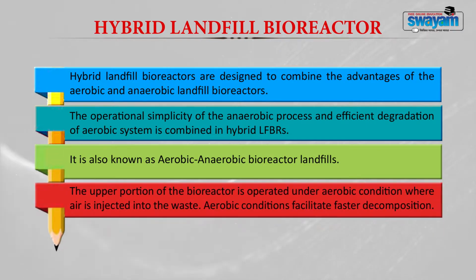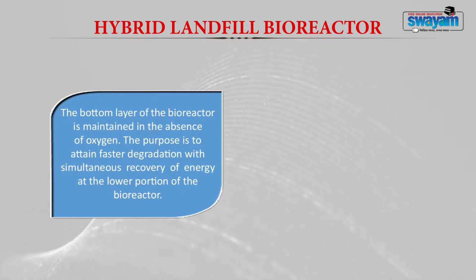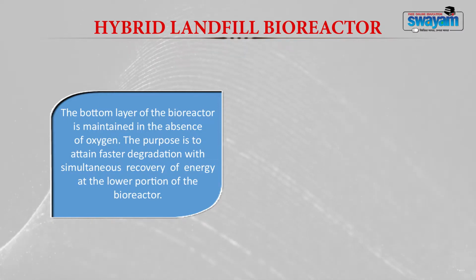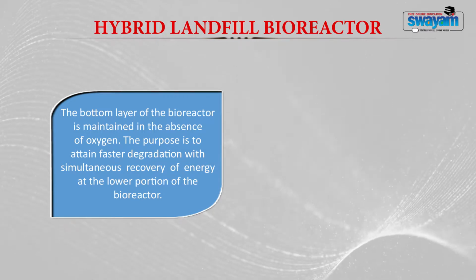The hybrid landfill bioreactors are designed in a way that the upper portion will be working under aerobic condition, where you will have a lot of pipes through which air is injected into the waste, and the bottom layer will be working under anaerobic condition, where you will not have any pipes for fluxing in air into the waste.